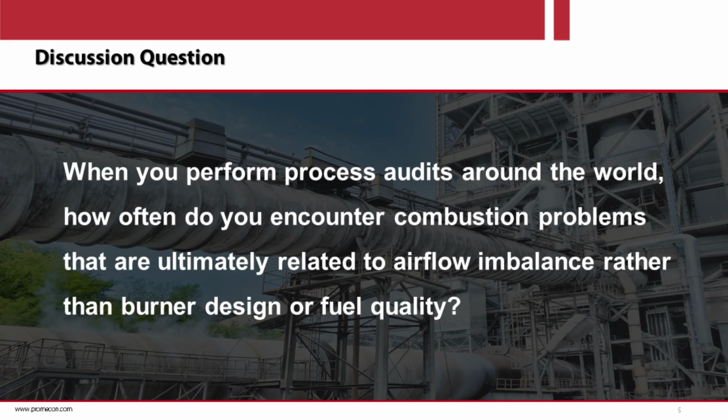On the other hand, the preheater exhaust oxygen is distorted by the TOC combustion of the raw material and, of course, the false air ingress in the tower. So you can measure it, but it doesn't give you direct information on the airflows because it's already quite far away and something is happening in between.